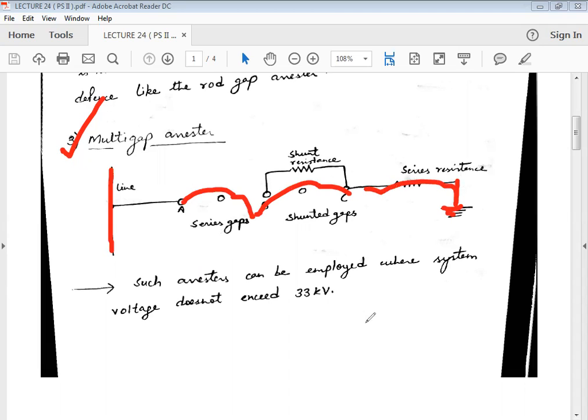When the fault occurs, because surges are temporary in nature, the surge remains for the shortest possible period of time. When the surge disappears, the shunt resistance comes into play. It will limit the current when the surge goes out and removes the spark from the B to C terminals, whereas the A to C terminal spark also goes out. So the arc automatically disappears.